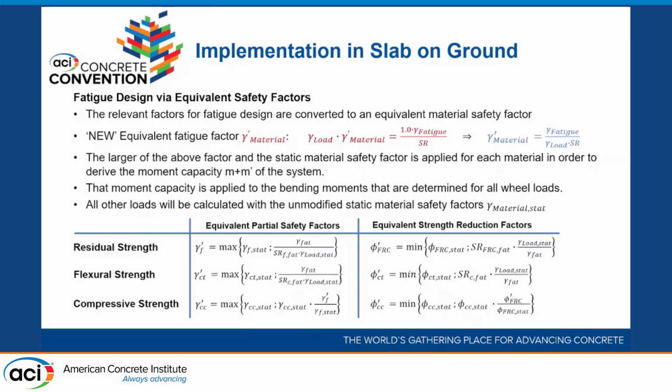This looks very complicated, but you can see the equation here: gamma factor, load, that's each one of these. This is obviously the European methodology. We have the partial safety and reduction factors that they apply to the material and to the different uses, as opposed to the way we do it here. But this is what is incorporated into our internal design tool as equivalent safety factors specifically for the case of fatigue.